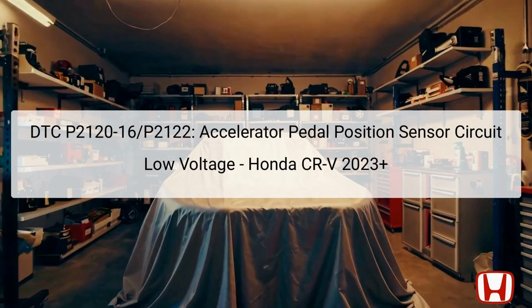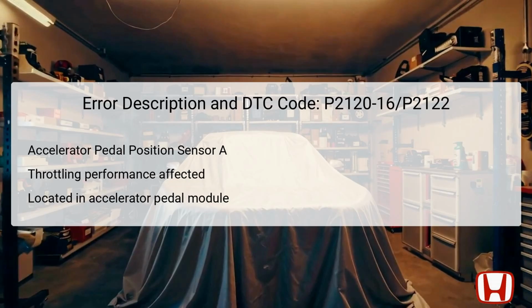If the voltage output from the APP-A sensor falls below a specified value, specifically below 0.2 volts, the PCM records this as a fault. Subsequently, this DTC is triggered for further investigation. Affected locations include the accelerator pedal assembly and the PCM, both of which play critical roles in vehicle operation and responsiveness.